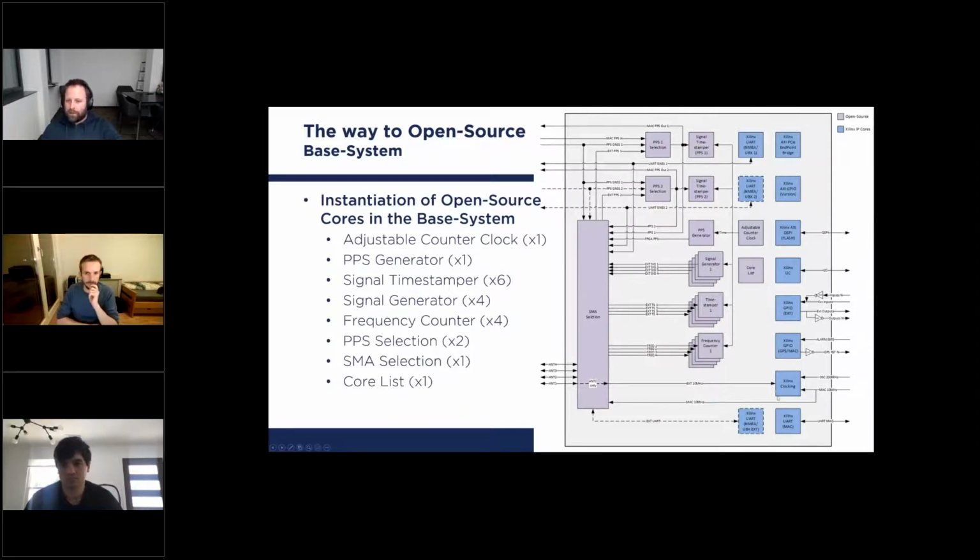First of all, I don't know whether all of them are freely available at no cost. Then it's a lot of driver adaptation. From the FPGA perspective, it would be rather simple to replace those cores by Intel IP cores, because that whole part here would be FPGA vendor independent. Of course, we need to change the pinout, but the main part is getting the driver up and running with other vendor-specific IP cores.